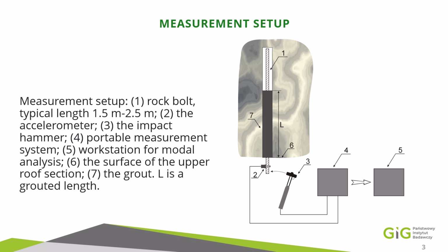Just to explain why. Generally speaking, a mechanical structure may be described by three matrices of mass, stiffness and damping. An equivalent counterpart to that model is a modal model, which consists of a matrix of natural frequencies and dampings and modal vectors.